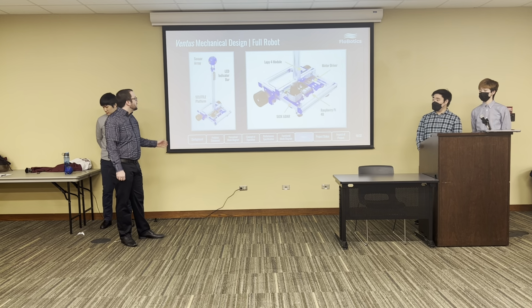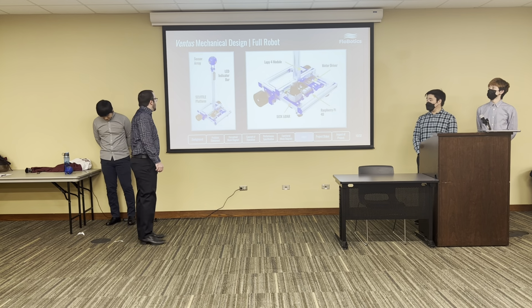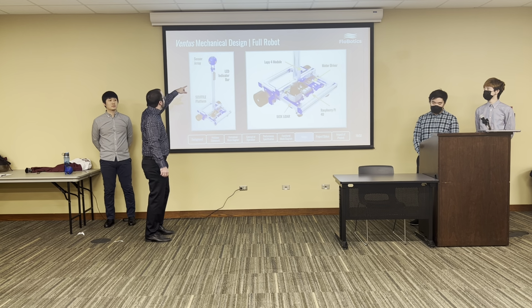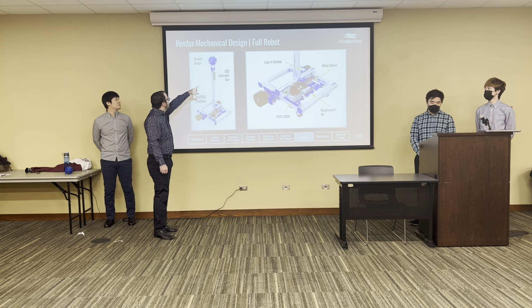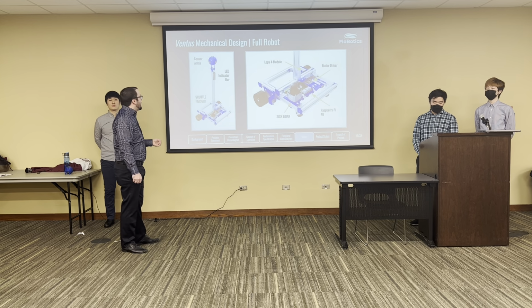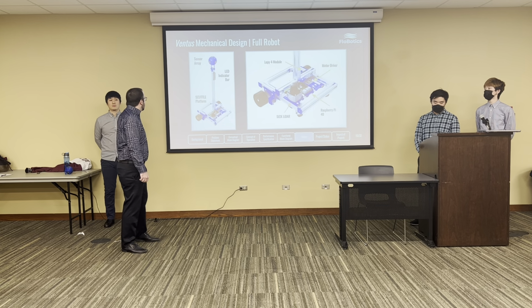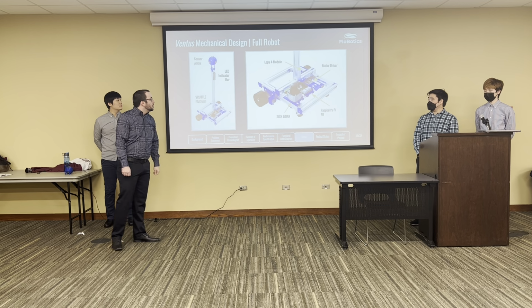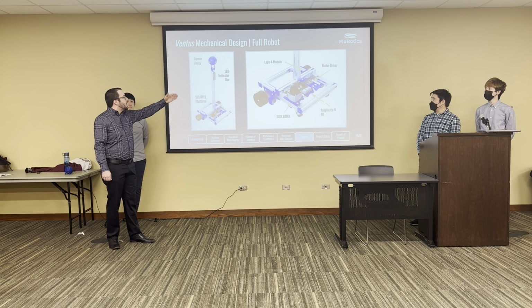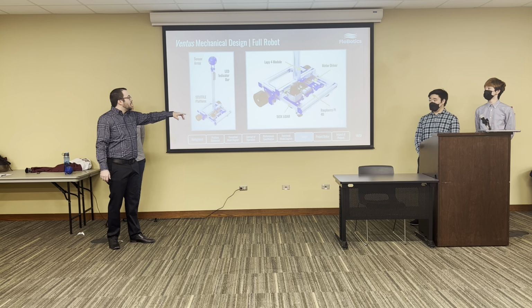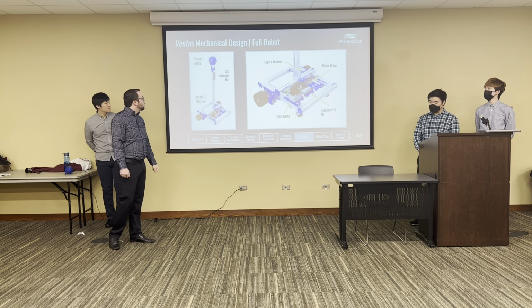All right, here's the full design of the Ventus robot. On the left, you can see the tower with our sensor array at the top. It has the BME 280, and then our LED indicator bar, which is a set of RGB LEDs, which we can control for status readouts, air readouts, and whatnot. And then our Scuttle platform on the bottom, which consists of the LoRa module towards the back, which will have an antenna mounted to our final enclosure, and then our motor driver, Raspberry Pi 4B, and the SICK LiDAR.